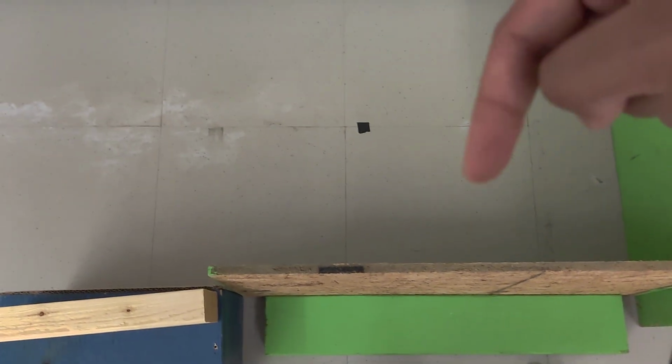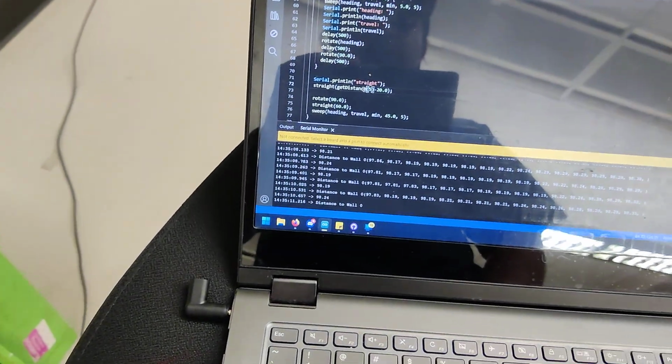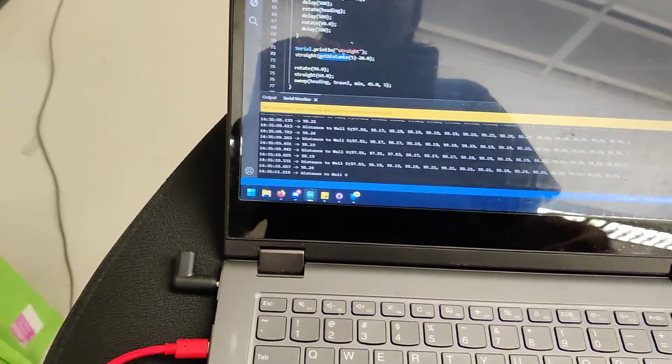Worst case scenario, if it's facing this bottom wall, it's going to rotate 90, face this guy, and when the ultrasonic is at servo position 180, it should grab this back wall, rotate towards it, and go straight out. So it'll take a maximum 2 passes in the worst case scenario, we expect 2 passes there. So that's going to eat up a bit of time, but not too much. But once we find our exit location, we move down, we grab a ultrasonic measurement of this back wall here. We say, go to that distance, come short by 20 centimeters. Just make sure we don't actually hit that wall.